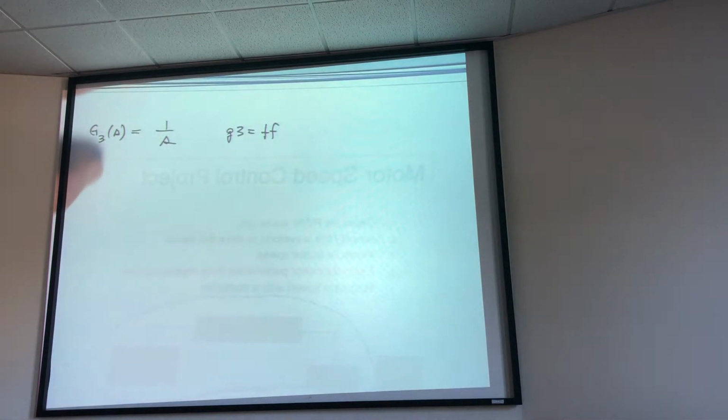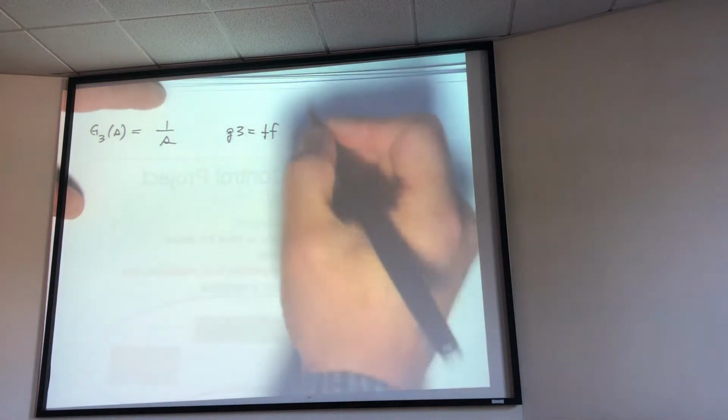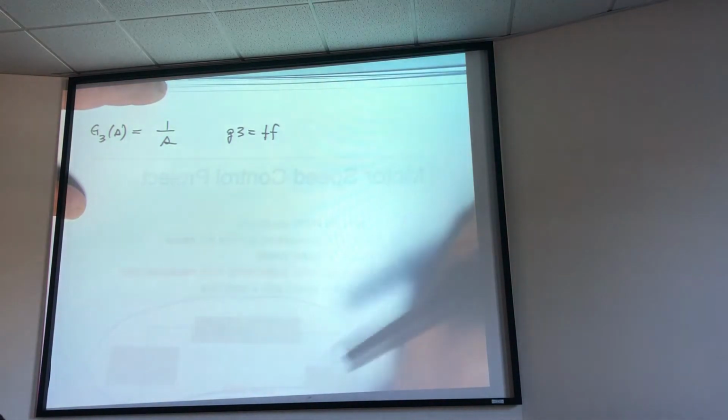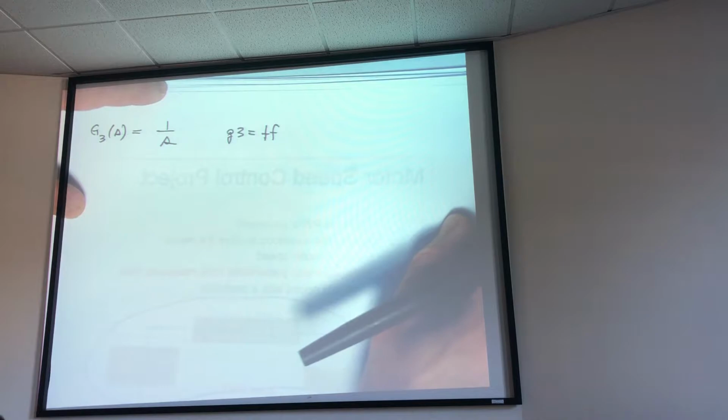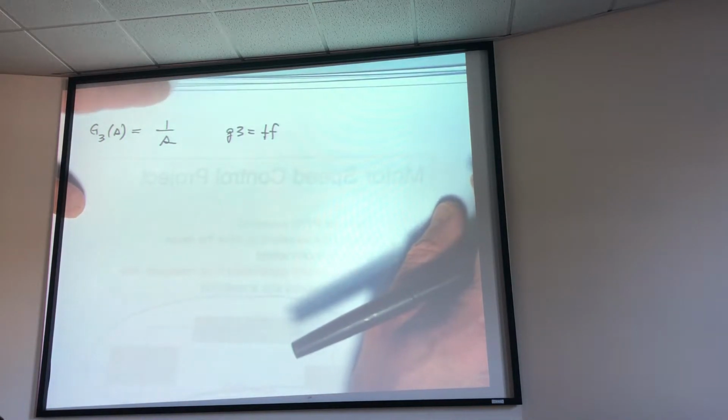It's an integrator. It's a pure integrator. It's the model of a capacitor, because the capacitor voltage is 1 over C integral of I dt. Or it's an inductor. I is equal to 1 over L integral of V dt. Did I say that right? Yeah, V equals L di dt.